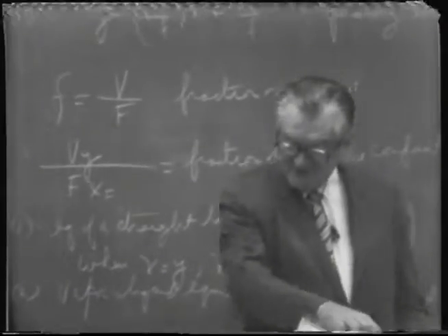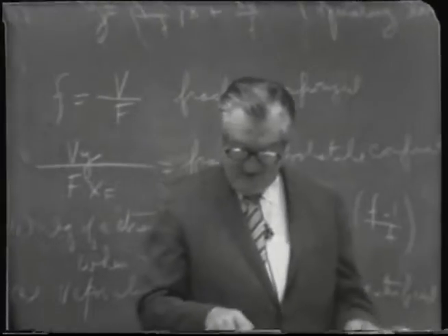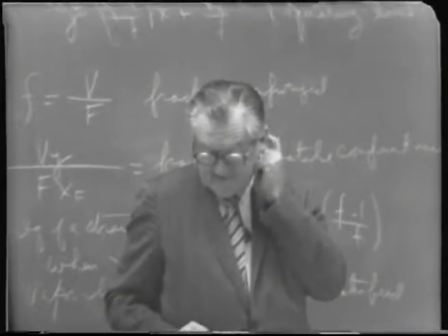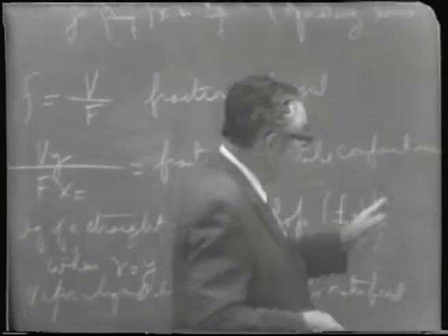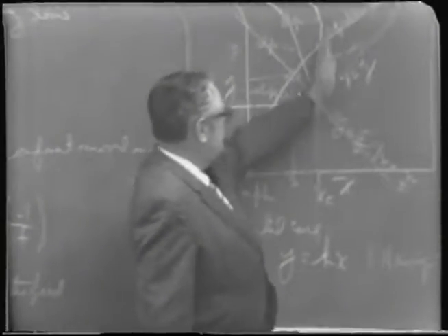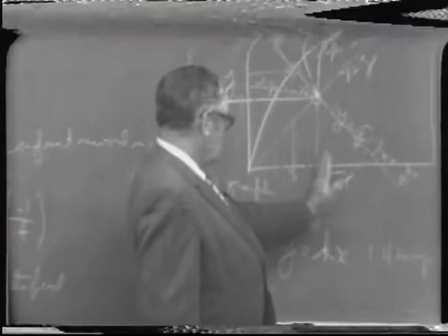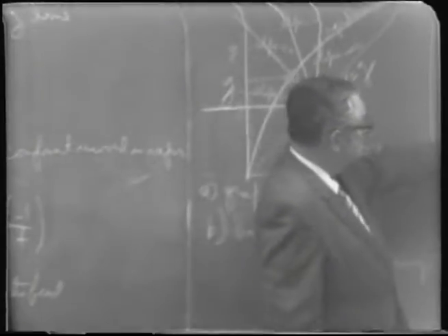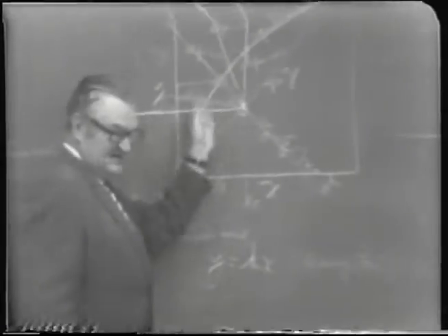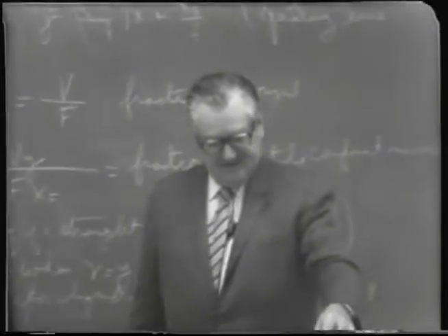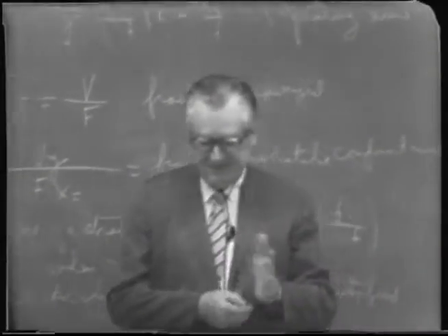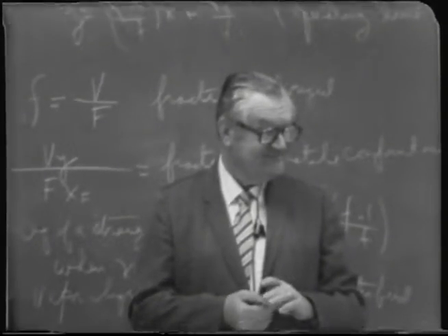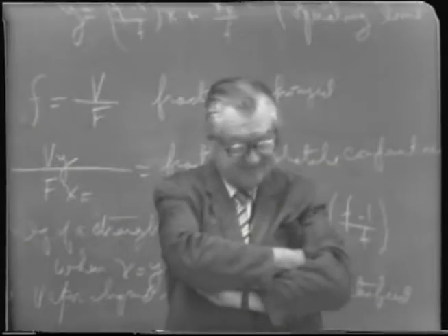So that brings up the next point. As I say, a hint here: carefully plot the equilibrium curve using mass percentages up to about 20% by weight. Any higher values are not needed because obviously we're going to be concerned with the equilibrium curve only to the left of x sub f. Because you see in every case here the slope is negative. It's over on the left-hand side. And also, this question is given in mass percentages, so there's no need to worry about converting to mole percentages, because you can plot the equilibrium curve on a mass basis.